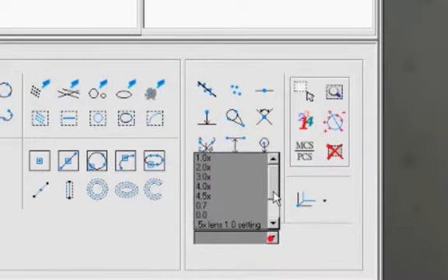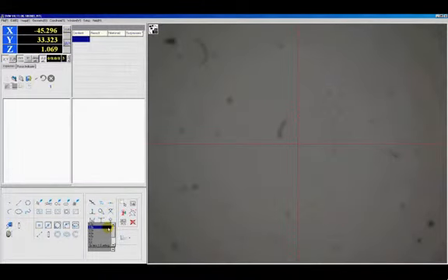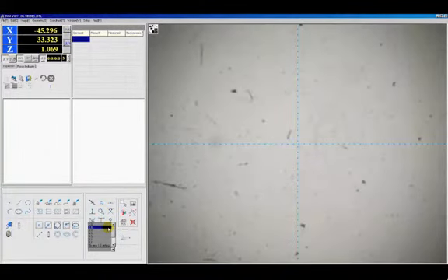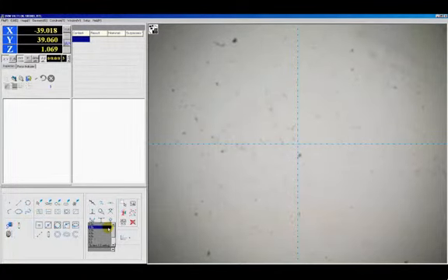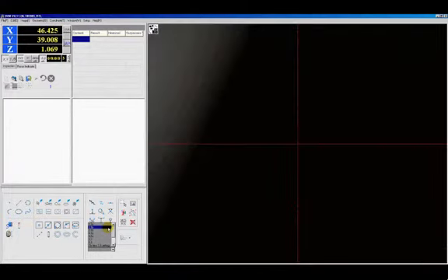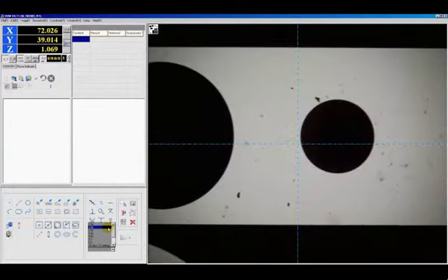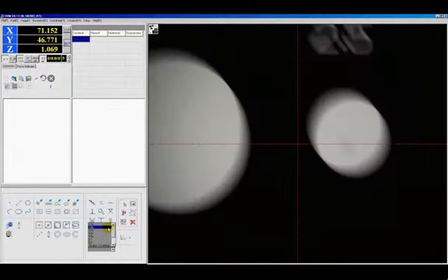Down here is the menu, which you can pull up to say which setting on the zoom lens you're on. So you'll notice markings or detents on the zoom lens which range from 0.7 to 1.0x, and this is where you would change that manually to tell it what setting you've zoomed to. So at first we're going to zoom down on the zoom lens to the 1x position, and we're going to use the glass scale that's supplied with the Science-Scope system to find the reference circle.